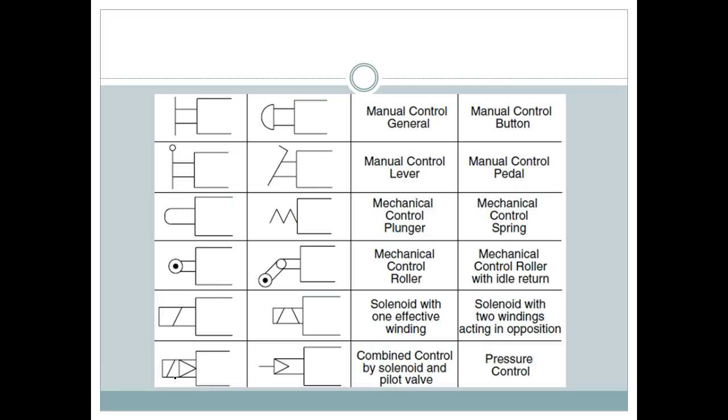So we got one of our robots over there now and it controls what we call a gripper, and we can't use it because it's the panic over there if you're in operation and programming. We can't use it now because we can't open and close the gripper because the valve is locked, the solenoid is locked. They're not stuck; they're burned up. And they are solenoid activated pilot. They're pilot seals.